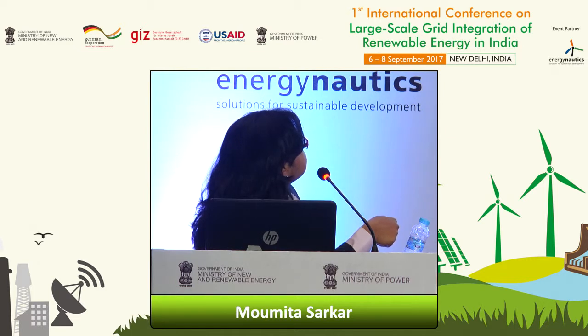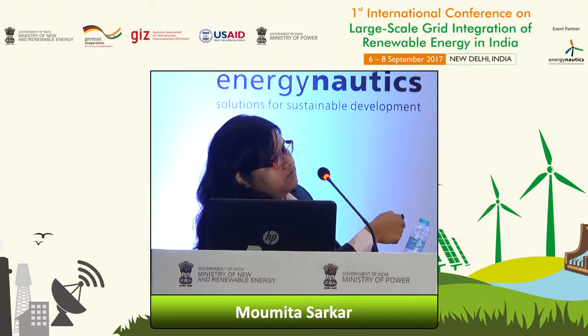We can see that the active power increases as the wind speed increases until the rated wind speed is reached. Along with the active power, the generator speed also increases until the rated wind speed is reached, but the pitch remains constant at low wind speeds.